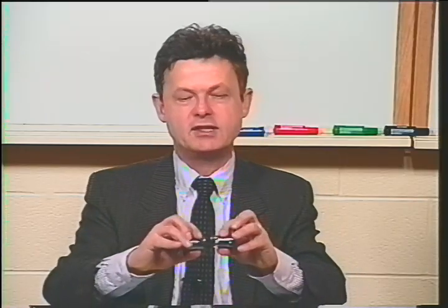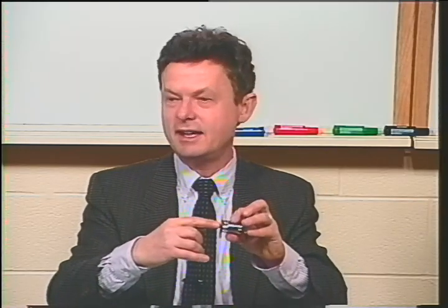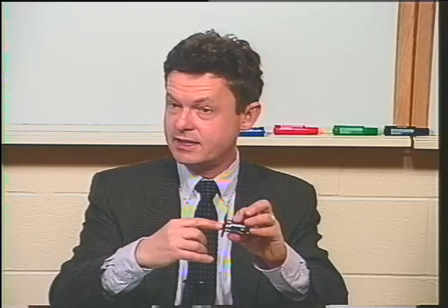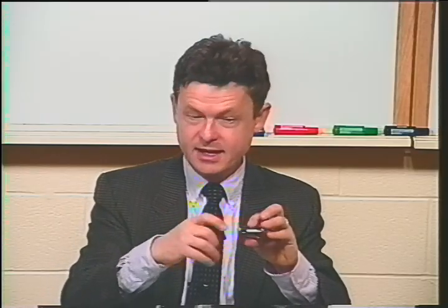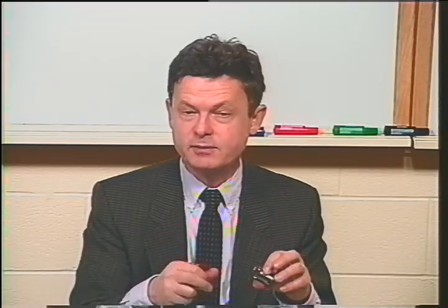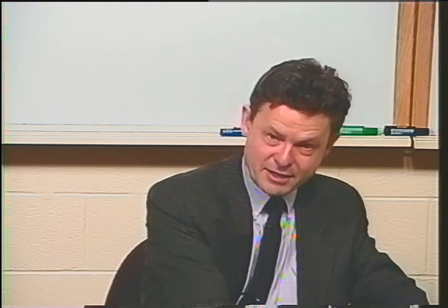In pipe flow, it's a function of radial position. And for the concentric disks, again, the shear rate is 0 at the center, maximum at the outside. So again, it's a function of radial position. Here, it's a linear function of radial position. For pipe flow, it's a more complicated function of radial position. But both are shear flow, and the formulas for describing the shear flow are exactly the same.